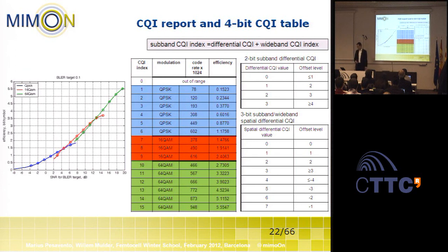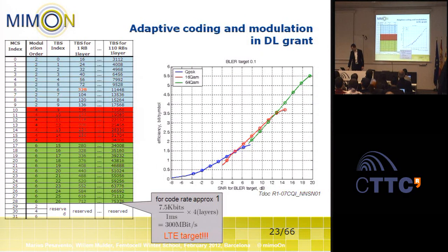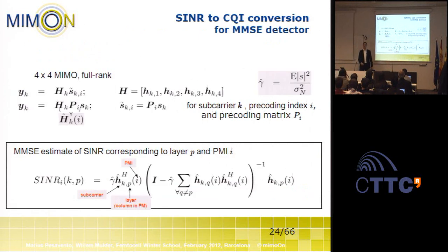There are also some more compressed schemes. Generally you need to report this based on a given bandwidth, so you need to generate several reports for each particular sub-band, but you sometimes also want to generate such SNR reports based on a larger bandwidth. So to achieve this, you need to have some way to estimate the effective SNR on this bandwidth.